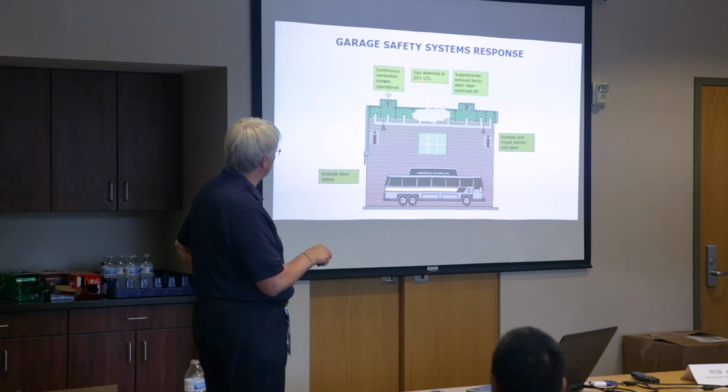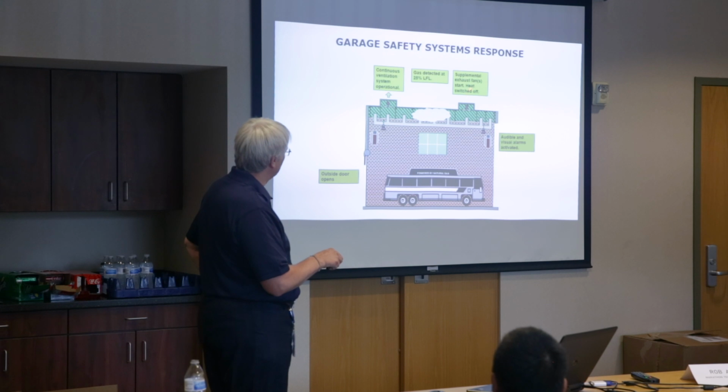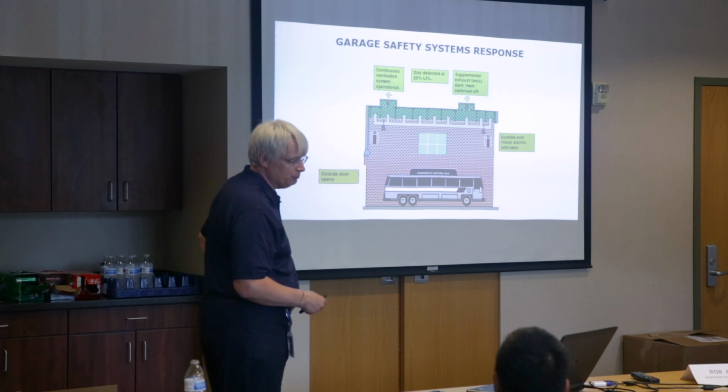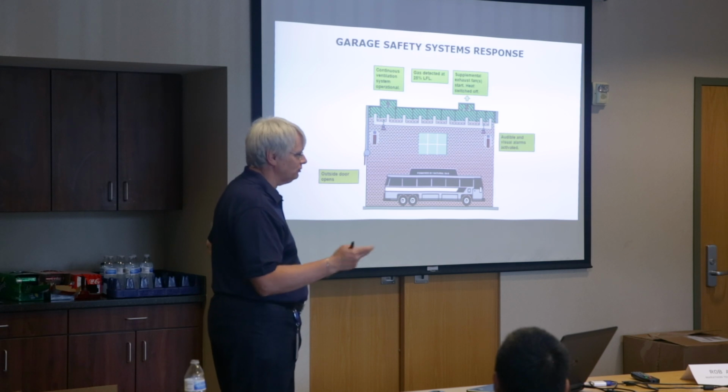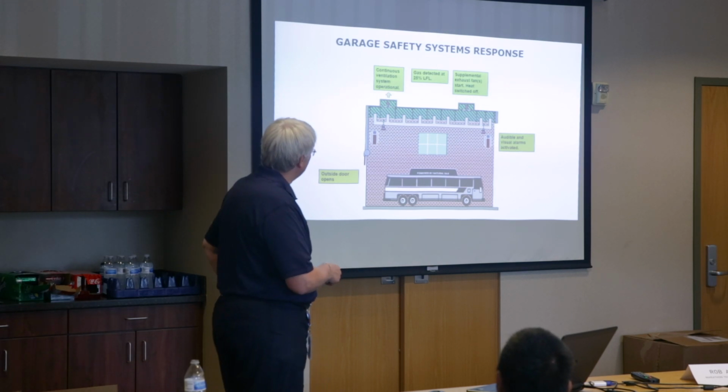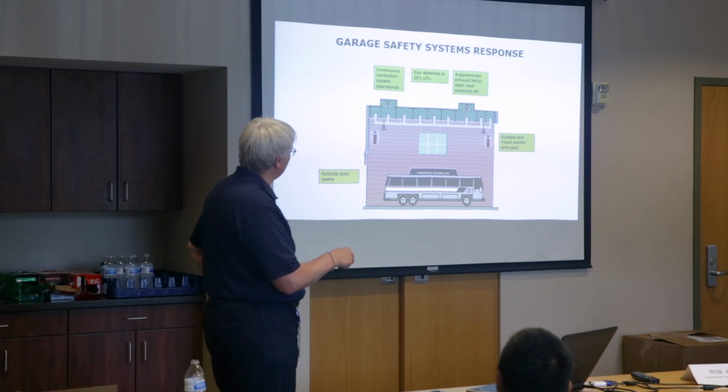The gas detection sees 25%. Our supplemental exhaust has switched on. Our outside door opened. Don't know whether you caught that or not. And we have audible and visible alarms. I have my computer muted right now because it's kind of an obnoxious sound. If anybody really wants, I can turn it on. But at any rate, that gives you an idea of what that looks like.